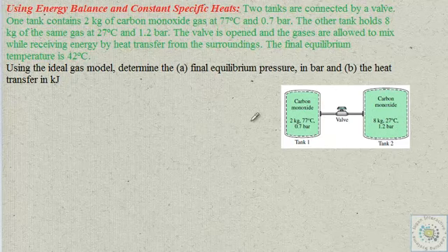So I think almost everything is given, like the pressure, temperature, the amount. So I hope that through that we can solve for actually the volume of tank 1, right? Volume of tank 1, and also we can solve for the volume of tank 2 because we are already given everything. If we use the ideal gas equation, then we can simply solve for that, right? I think that it will not really be a problem how to solve for the volume.